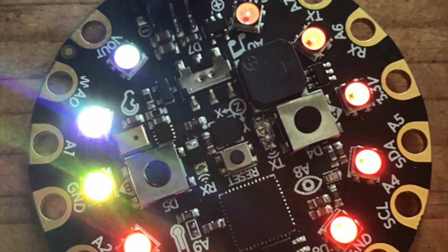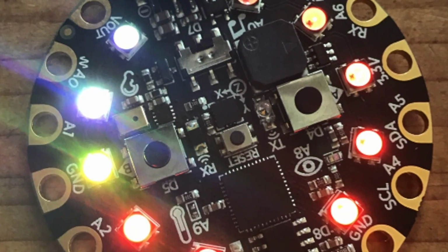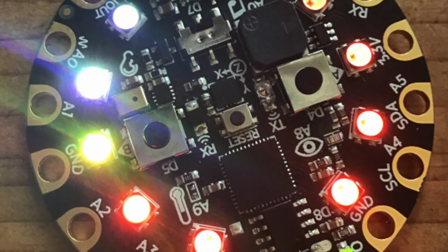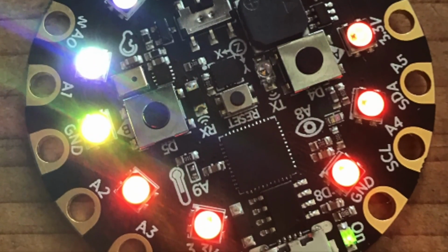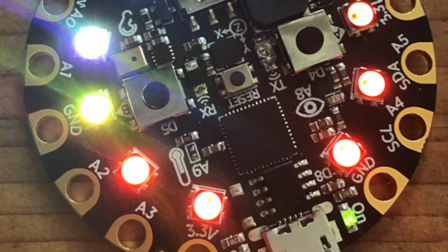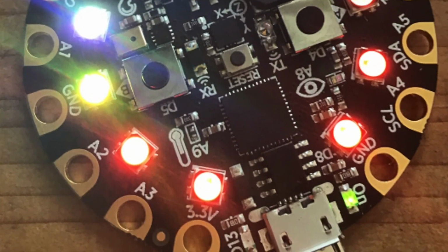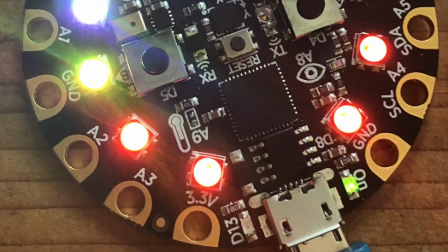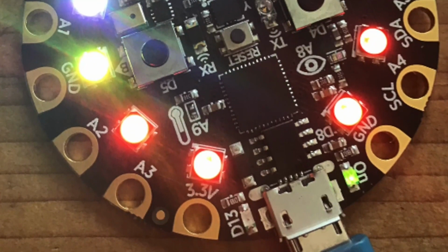If your Arduino freezes at any point during lighting programming, power down the Arduino and your lighting power supply. Disconnect the lights from the Arduino and then power the Arduino up again. If you don't see freezing with the lights disconnected, this is an indication that you need to add external power to your LEDs before you continue.